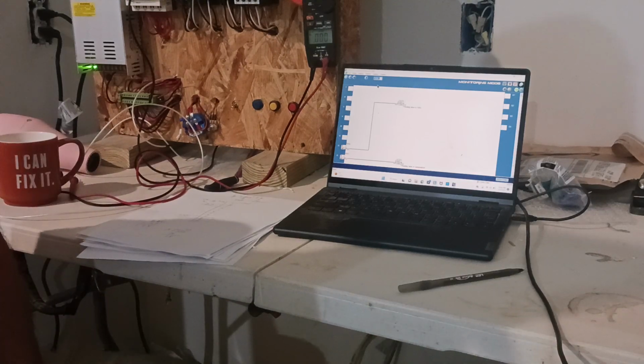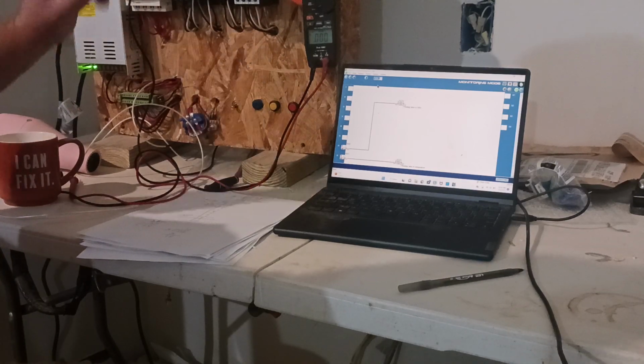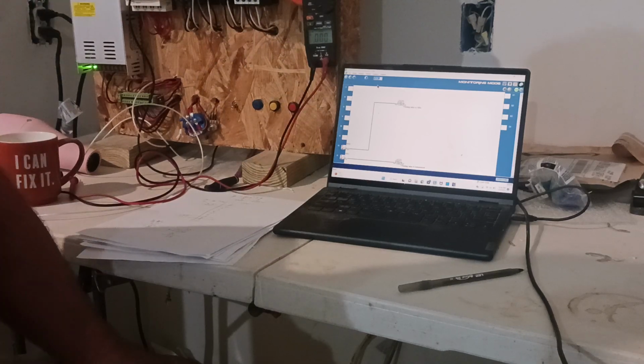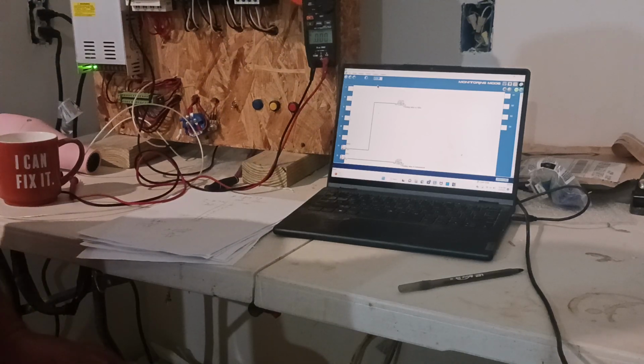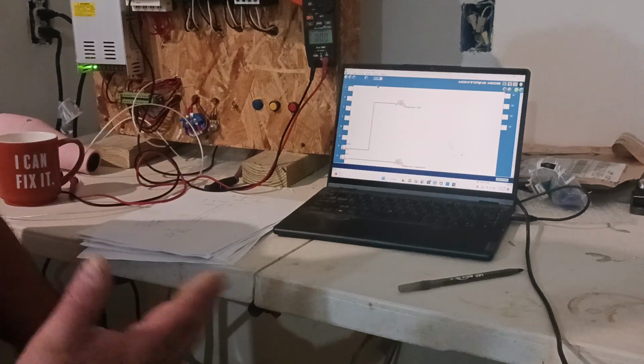And that's called analog. And there's two different types of analog. There's a current type and a voltage type. We are actually going to be talking about the voltage type because this PLC only takes the voltage type. In this case, it's 0 to 10 volts. And so what is a 0 to 10 volt analog input channel? Well, it accepts anywhere from 0 to 10 volts, right?